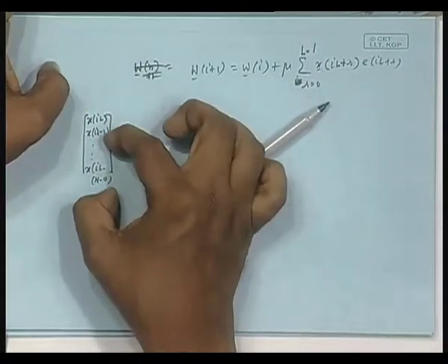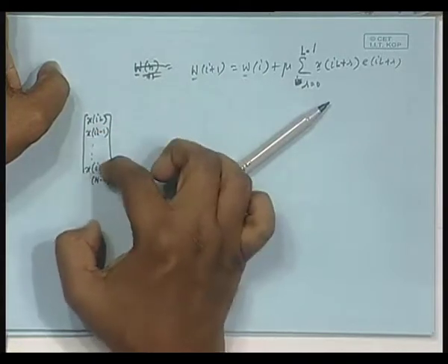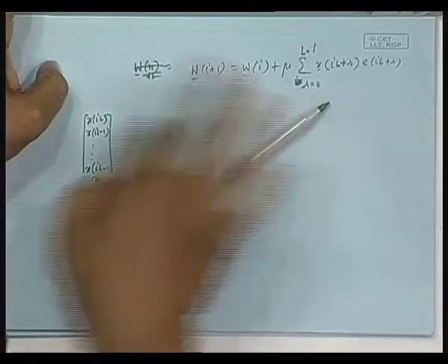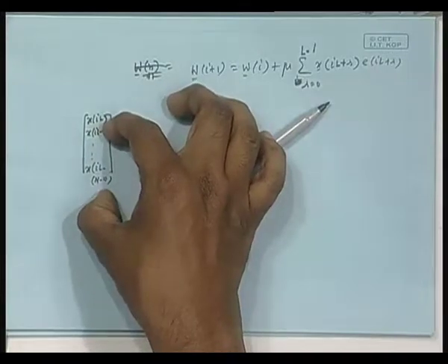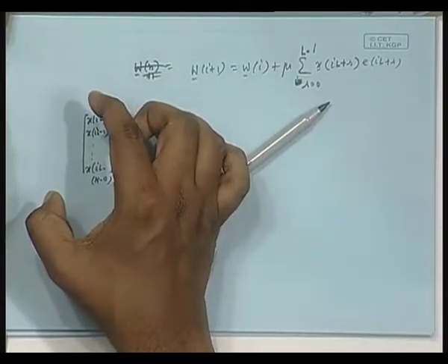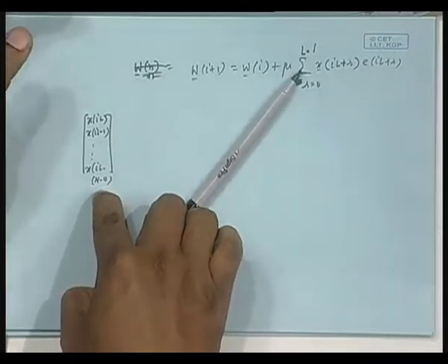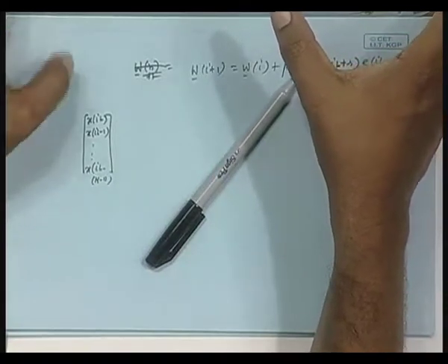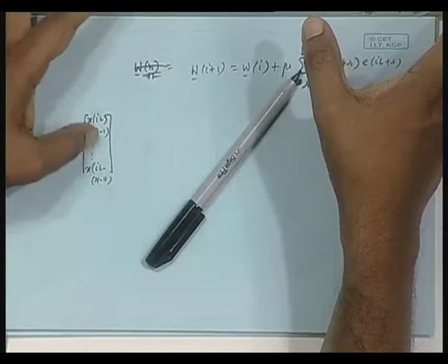So, this is that overlap zone. I will take the last N minus, not M anymore, the filter length is not M here, it is capital N, I have just changed it. The last N minus 1 data from the previous block correspond to that. In my modified scheme, they have been appended to the current data block. The current data block earlier was starting here, but I have appended this part.